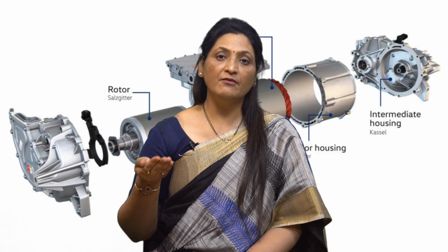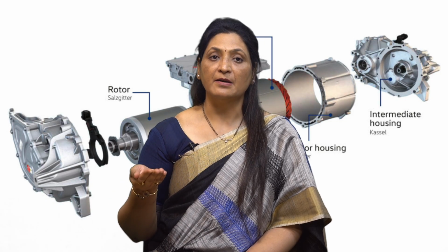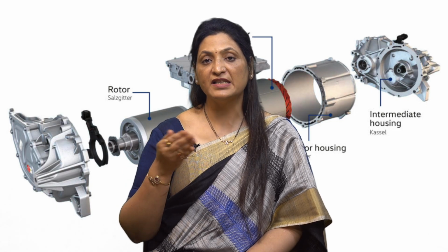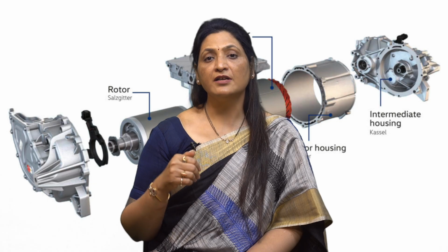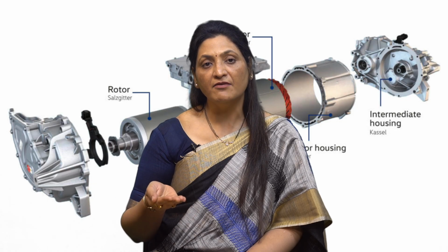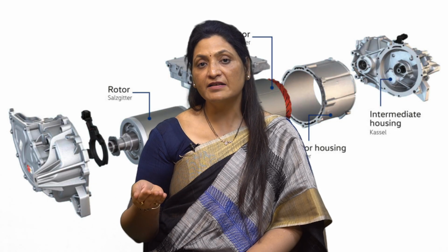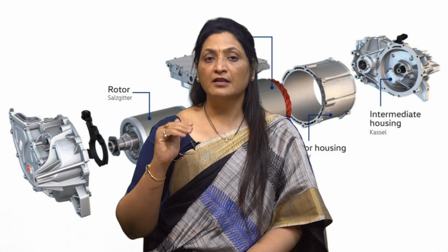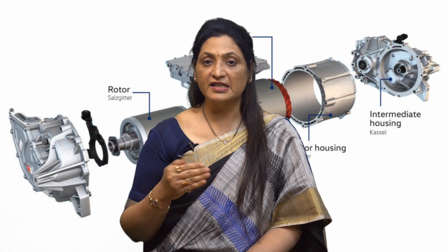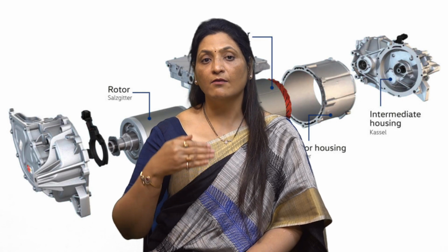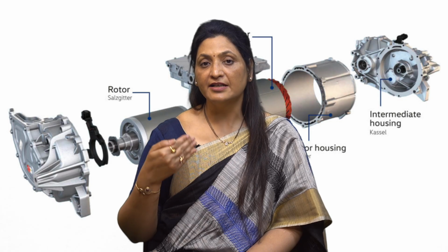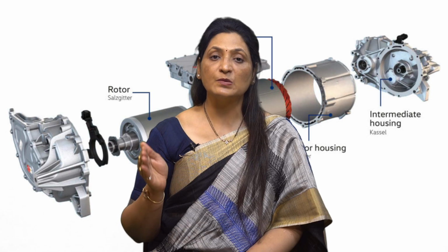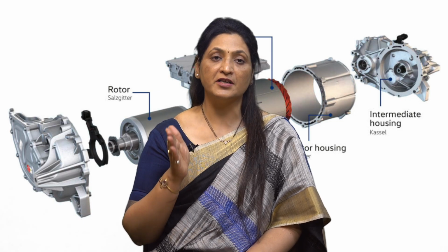The motors available are AC or DC, but the availability of supply decides the type of motor to be selected for the drive. There is a possibility of supply frequency variations, and the motor selected must be able to withstand such supply variations. The size and rating of the motor decide its initial cost, while the various losses and temperature rise decide its running cost. So, the economical aspects must be considered while selecting a drive.